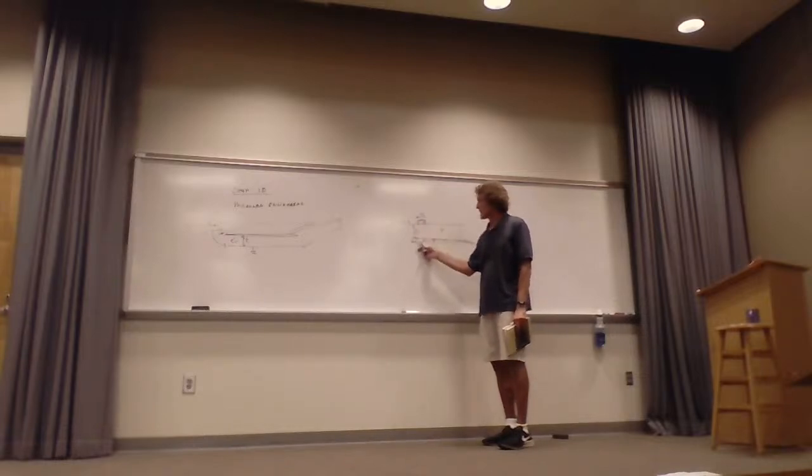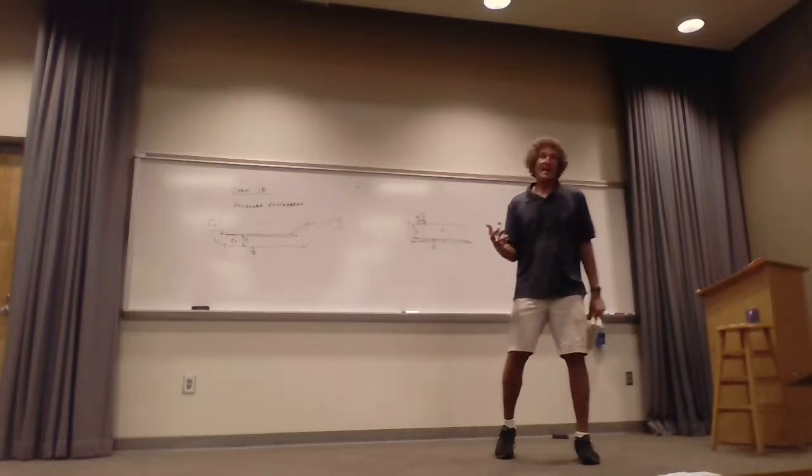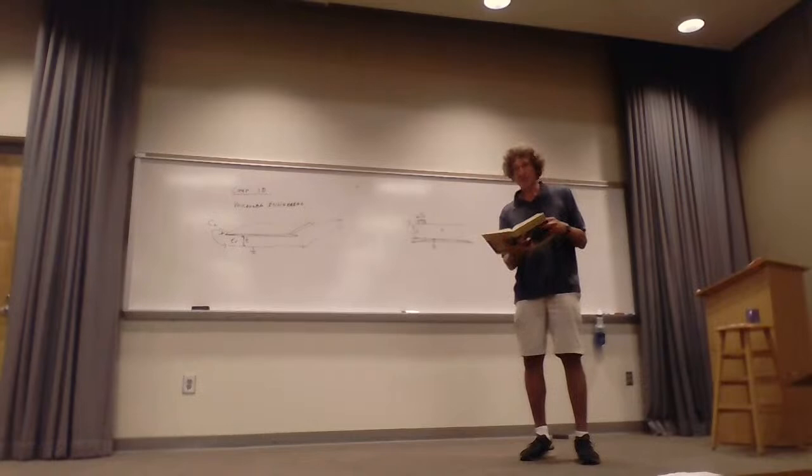Right? Width to thickness here. And there are a cajillion formulas out there for that, but they're all canned formulas. They don't come from first principles. Somebody didn't solve Maxwell's equations and get a closed form of the solution, at least not that's used. They have something that approximates the solution of the impedance based on W and the height.